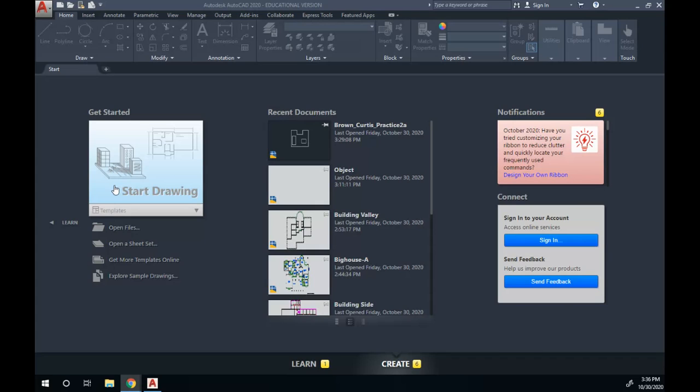The purpose of the projects is that you can take what you've learned from the previous chapters, for example chapter 1 and chapter 2, and apply it so that you can draw this bracket without having exact instructions. Here it says in this project, you will create a simple drawing using the commands open, line, circle, rectangle, save, erase, and undo, as shown in figure 3-1.